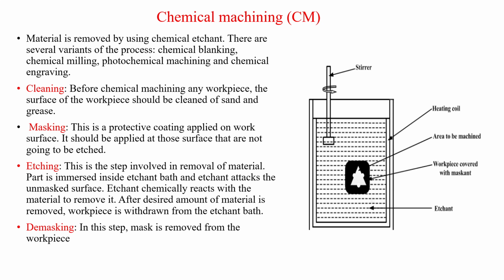So here basically we have seen various non-conventional processes. In mechanical we have seen ultrasonic, water jet, abrasive jet, AFM, abrasive water jet, and the use of magnetic processes. Then we have seen EDM, ECM, the plasma arc process, then chemical machining. These are the various processes which use either a mechanical or a thermal process for removing material without the tool being in contact with the workpiece.